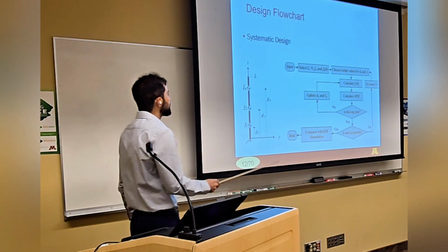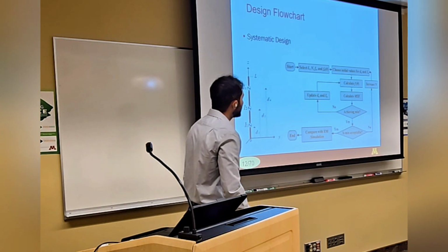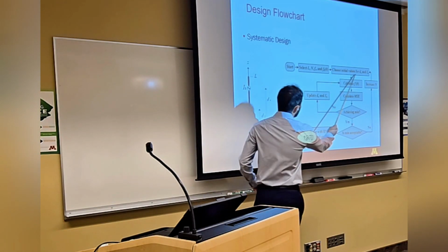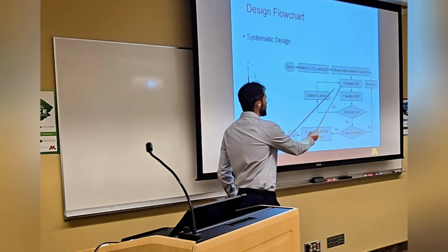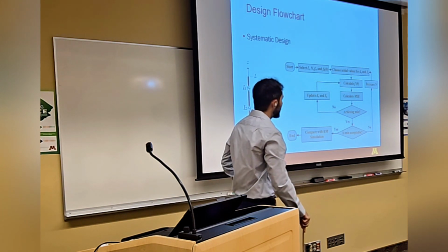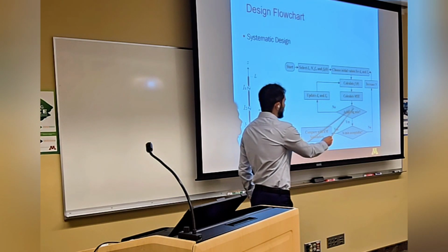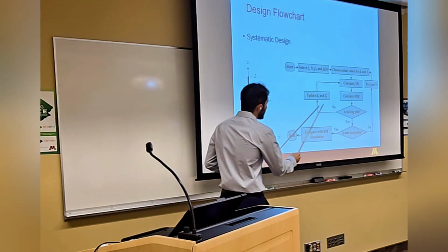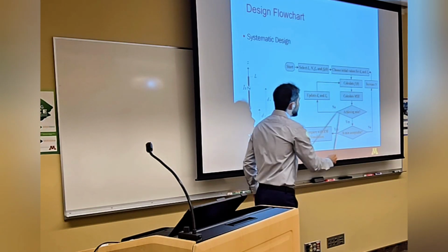Firstly, we select the ideal radiation pattern, center frequency, and length of the antenna based on the required beamwidth. Then we select initial values for the location and excitation of each port. Then we calculate the radiation pattern based on these initial values, and compare it with the ideal radiation pattern. We compare using the mean square error metric. Based on this error value, we update the location and excitation of each port, and we do this process